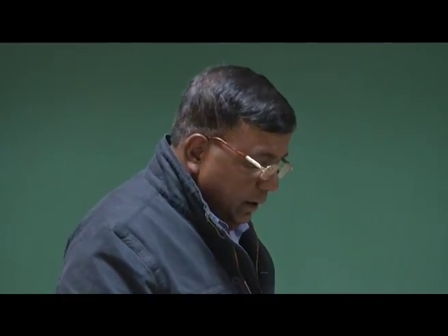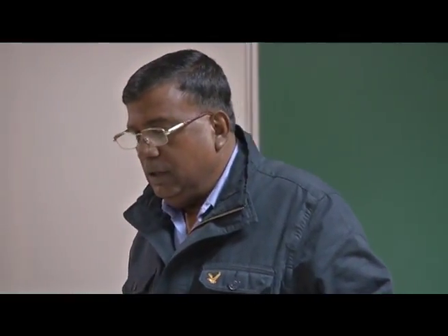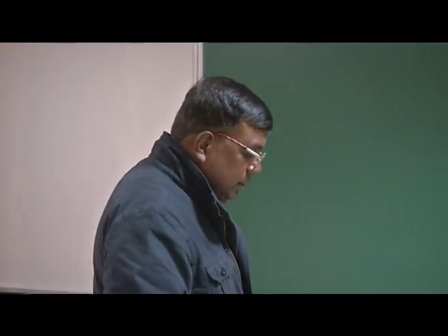Good morning. So far we have been discussing the static stability part of it, from elevator required to stick force requirement, as well as the gradients. For example, elevator per g, d delta E by dn, then stick force per g, all these things we have derived. And at the end you realize that a lot of equations were there, but now once we understand the static part of it, we need to go for dynamic stability.